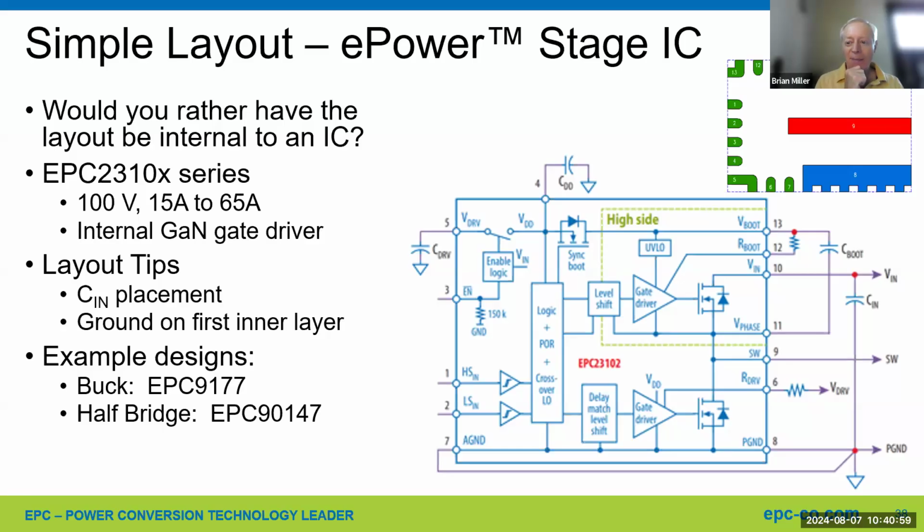I would say that some of these drivers, for example, the onsemi one, have built-in LDOs for the top, and they assume you're going to boost something like 12 volts, and then it regulates itself down to 5 volts internally. So in those kinds of cases, you don't have to worry about a low drop.